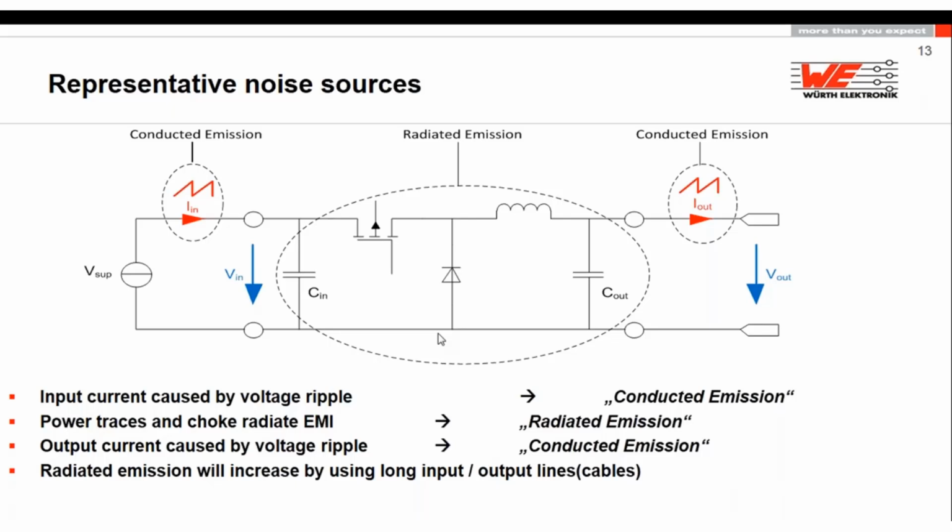Please, because of this reason, don't push the auto routing button. If I were the manufacturer or the programmer of this software, I would rename the button to "make EMC problem" button. Don't push this auto routing button. Please take care that this track is as short as possible, as low impedance as possible, because this is your major radiation point in the anechoic chamber.